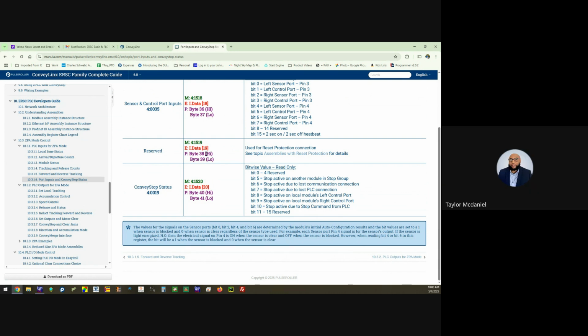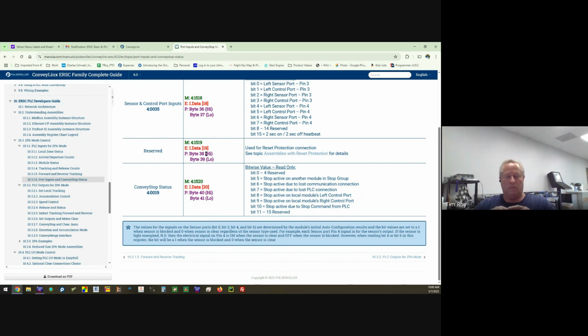In PLC mode, if a downstream piece of equipment is not ready, that would be one of the bit conditions in the motor run logic. Downstream must be ready. And if that's not on, you can't run the motor.